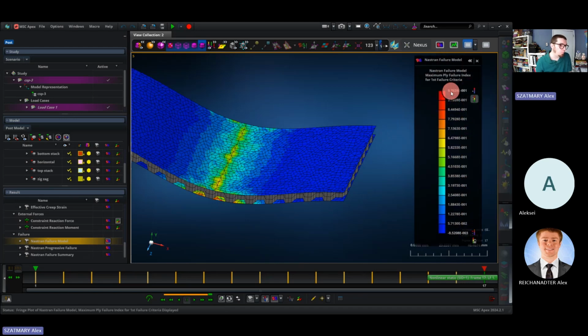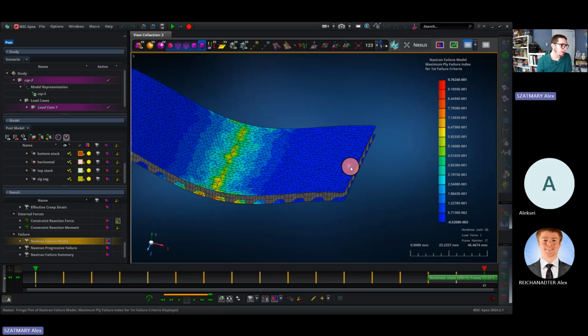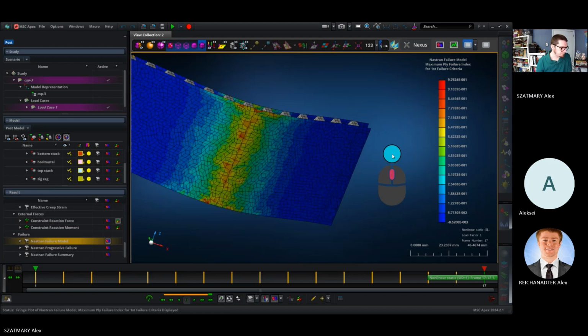On this scale, 1 means that it has failed, and something like a 0.5 means the equivalent of some of the fibers having snapped. As a composite fails, it can locally lose significant stiffness, causing it to relax a little bit, but then putting more load on related areas. And so failure can propagate in complex ways across composites.